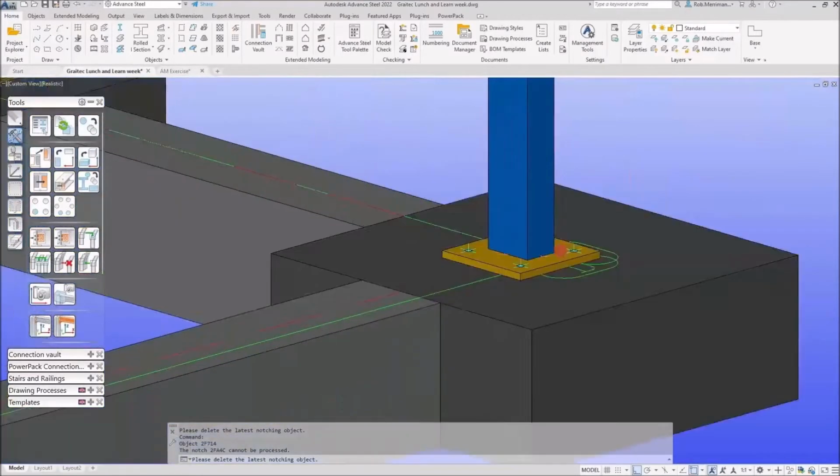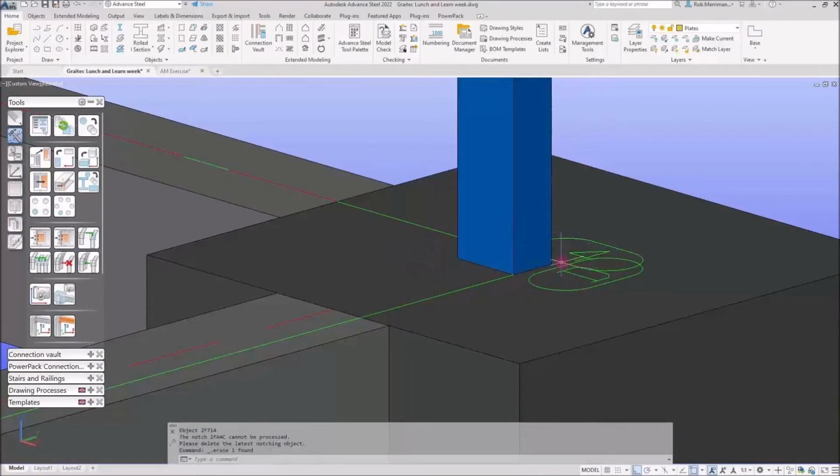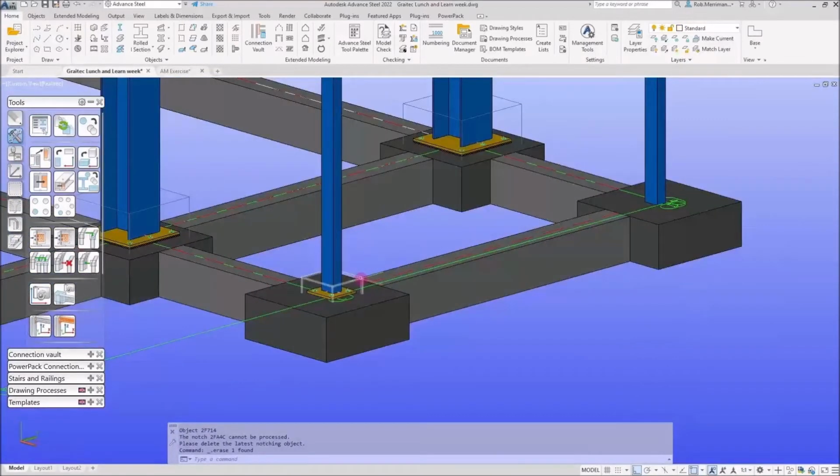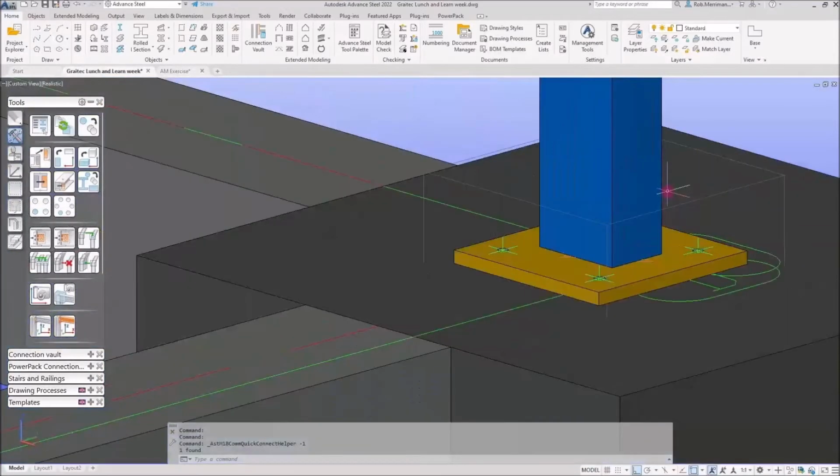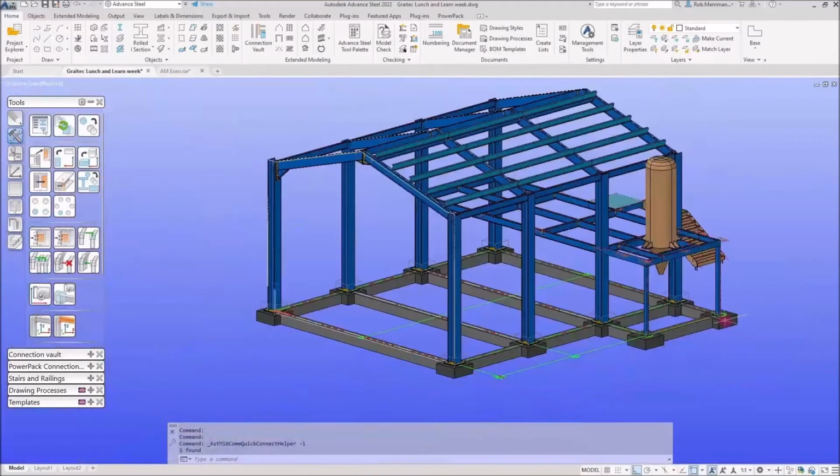If I take this joint off, and I select, you've got to select the joint box, I right click and choose propagate joint, that's going to put that on there. Now the benefit of propagating is you don't have to select everything. So for joints that have single inputs it works really well.